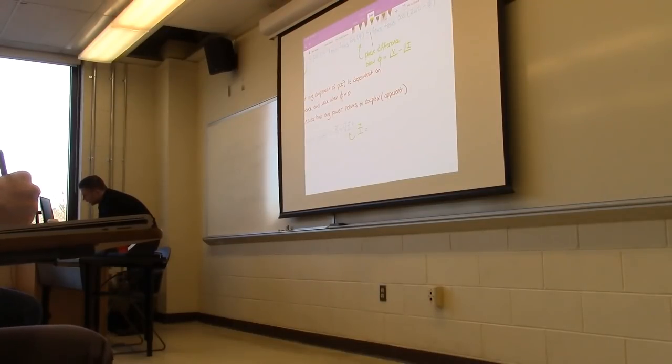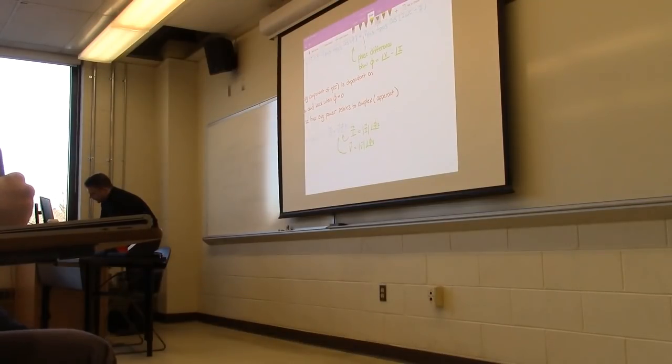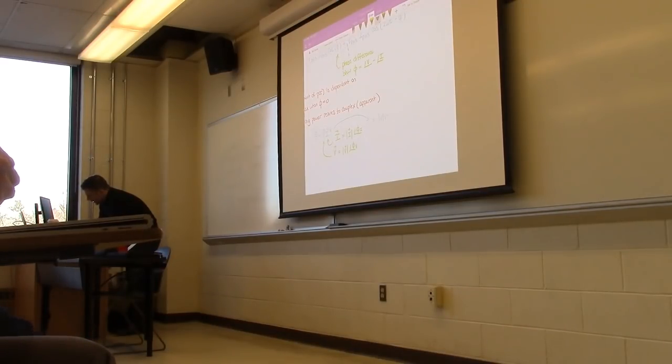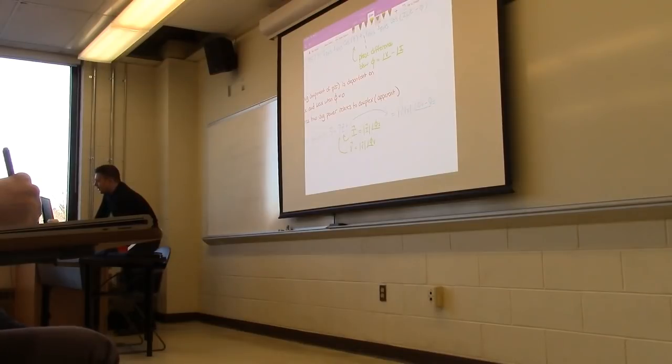So I will be equal to, similar to before, magnitude of I and angle phi sub I. V will be equal to this. The subscripts will tell us whether it's associated with the voltage or the current, and if I go ahead and break that out, it'll be equal to magnitude of V times magnitude of I times the angle V minus the angle I. Right, so that's the definition of complex, also known as apparent power.